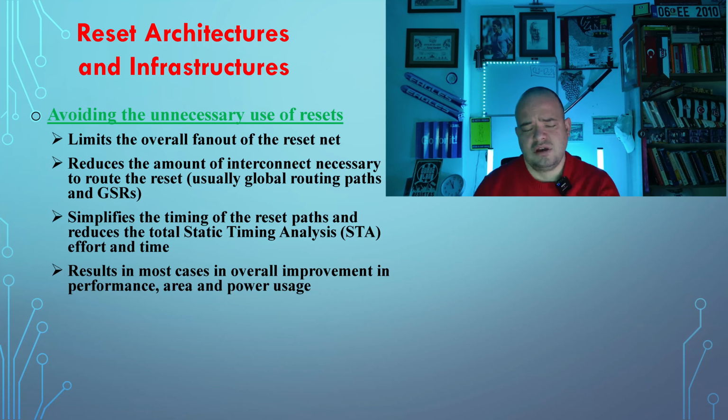But otherwise, if you have, let's say, 7 clock domains, and each clock domain reset fan-out is more than 1,000, then you are getting some bad effects in terms of performance, area, and power usage. So resource usage, a lower Fmax, even negative slacks, of course depending on your constraints, negative setup, hold, recovery or removal slacks, and of course power usage is also increasing.